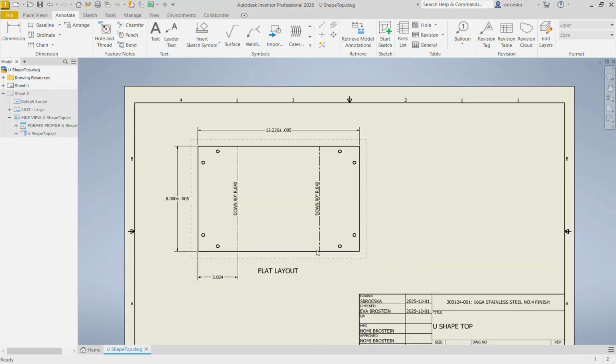A sheet metal brake only makes up angles. So you might say, oh, how do you make a down angle? Well, you turn the part over and you bend it down with respect to the other angles.